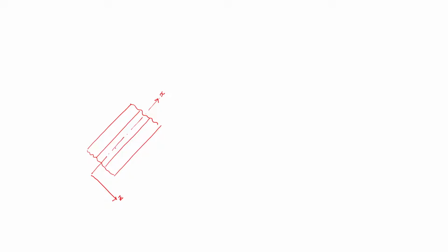So the mid surface will pass through the central layer, isn't it? So if you actually try to find out what is Zk for this, this is Z1, Z2 is 0, and this is Z3. For the middle layer, it will be 0. That's all, because the mid surface of the middle layer and the mid surface of the laminate do coincide. Therefore, it's 0.